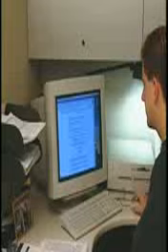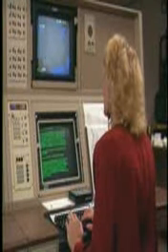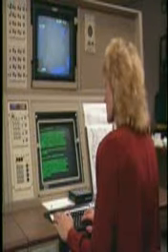NOTAM L information is only maintained by the local FSS that is responsible for the airport and is not distributed outside the coverage area. It can include such information as men and equipment near or crossing the runways, taxiway closures, and airport lighting outages. FDC NOTAMs are issued to amend instrument approach procedures and aeronautical charts. It is extremely important to check these prior to an IFR flight and update your flight information where necessary.